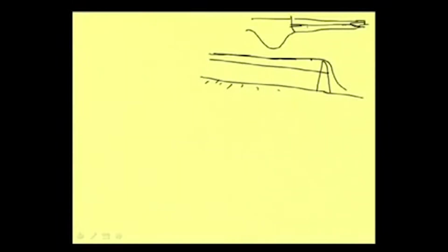Now, this water surface that we are having here is not a uniform flow, because this depth is gradually increasing from section to section. Here depth is y, and suppose on the upstream we can have normal depth, and then it is gradually increasing like this. So, at this point it is normal depth, but after that it is gradually increasing and we are having different depths y1, y2, y3, y4 like that. And this flow is nothing but one example of gradually varied flow.